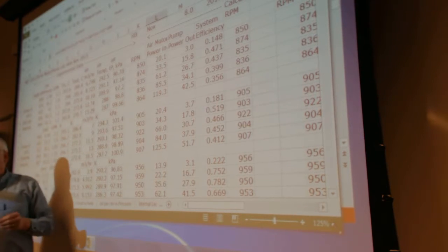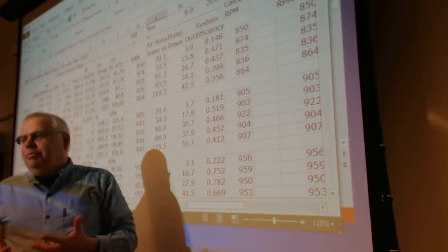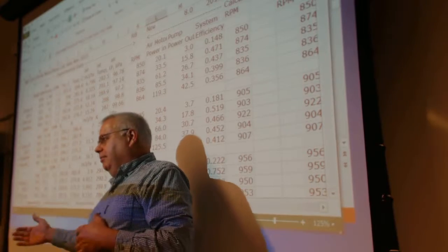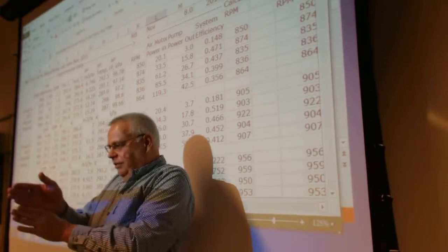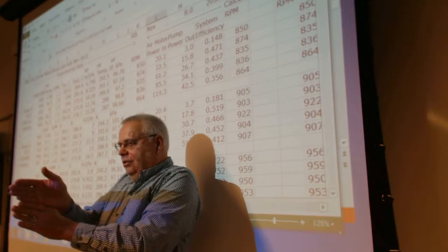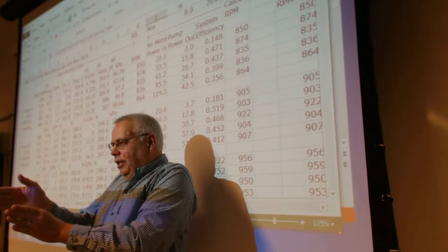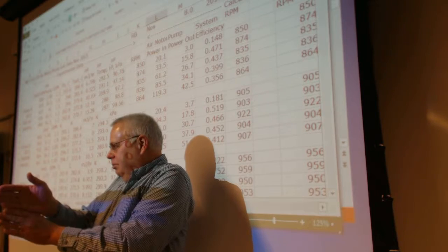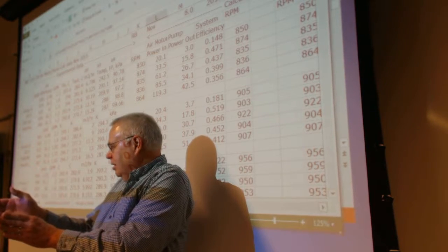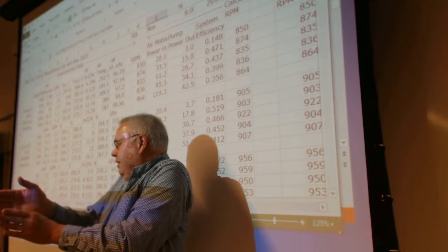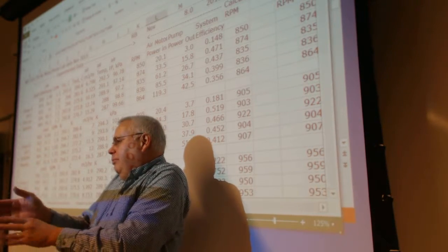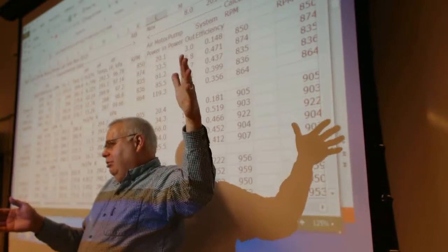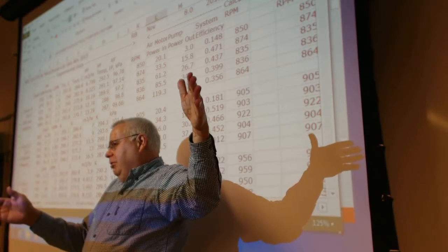Some of the errors people had involved the amount of work the pump is putting into the water, from the suction side up to the power side. It started off at 0 on one side, there was a negative. As you started pumping water, it had to suck, so the pressure went down on that side. It may have been like 5 psi and it went down 3 psi, it went down 2. Well, some people subtracted that from the high side. So it was 20 pounds here, and 2, it should have been 22.